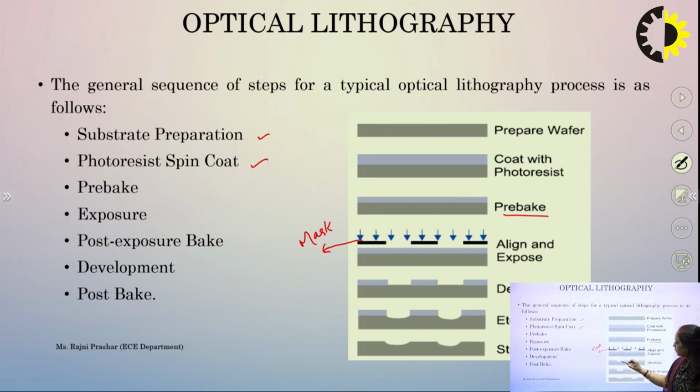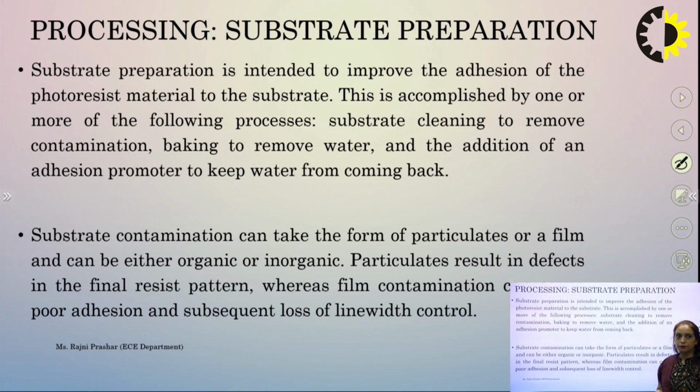Then the silicon dioxide is removed, and finally the PR is removed, since its function is complete. After post bake, it is ready for the next steps.